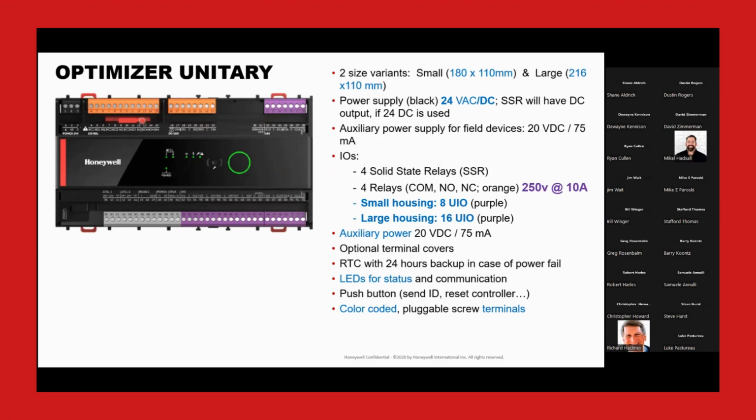This red jumper here physically brings all the relays to the same source common, so that if you just want to run a 24 volt or 120 or 240 volt supply into it, you can have them switch that directly, or you can pull this jumper out and do each relay individually. If you are running line voltage, you will want to buy the optional terminal covers that cover up the terminals, keep you from getting shocked. And the best is yet to come.